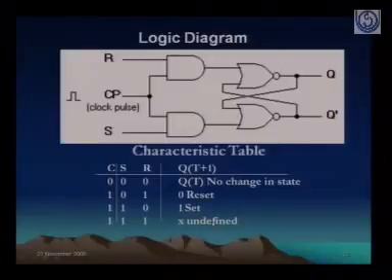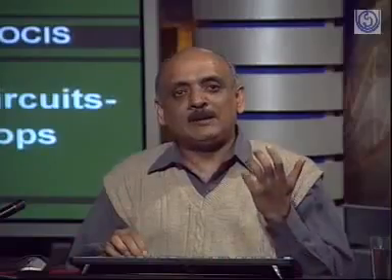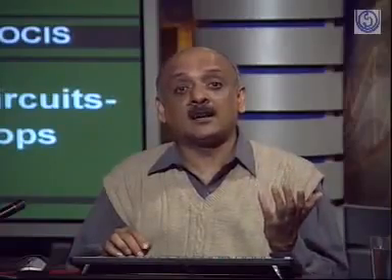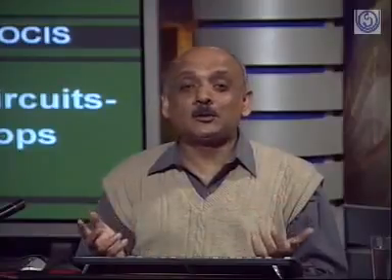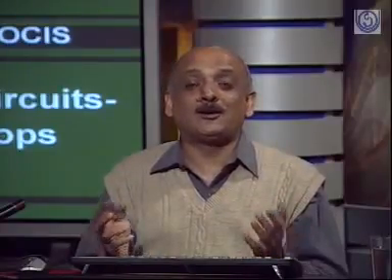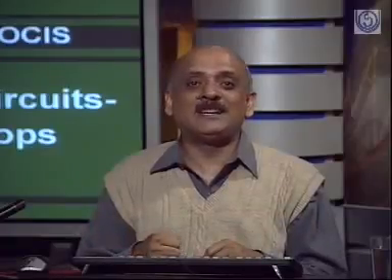We don't know based on which flip-flop it comes or what happens inside. We don't know about this particular state. So for this particular flip-flop that we have defined, the SR clocked flip-flop, if both of these values go to 1 and 1, it is not defined. In fact, it is then our responsibility, if we are using this flip-flop for designing circuits, to make sure that the 1, 1 state doesn't occur, because if that state occurs, we don't know what state this flip-flop will be in after that.